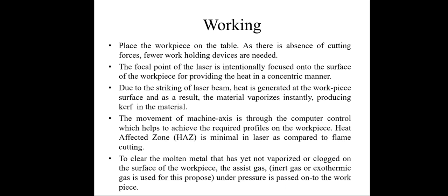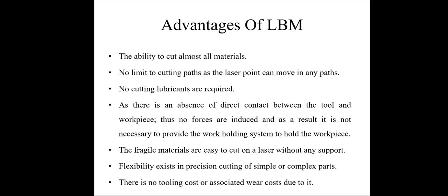The heat affected zone is minimal in laser cutting as compared to flame cutting. To clean the molten metal that has not yet vaporized or has clogged on the surface of the workpiece, an assist gas, that is inert gas or exothermic gas, is used for this purpose. It is passed under pressure onto the workpiece. Next, we'll discuss the advantages of this laser beam machining process.